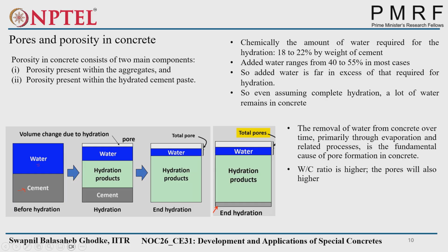After some time, what will happen? This water will also evaporate, and this will create total pores. And if we consider that some unhydrated cement paste is there, then the total pores will be less, because some of the cement is unhydrated. So the pore volume will be less compared to this one.